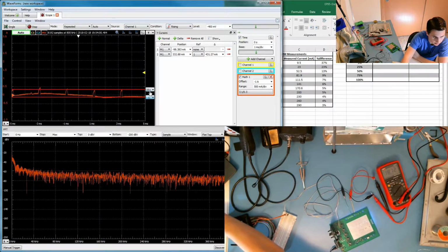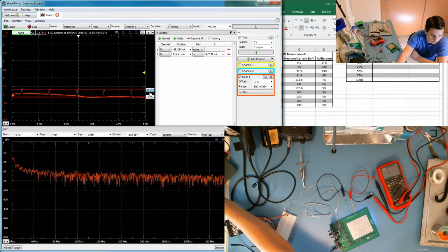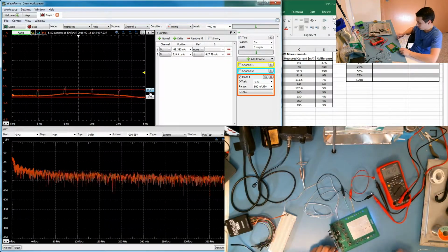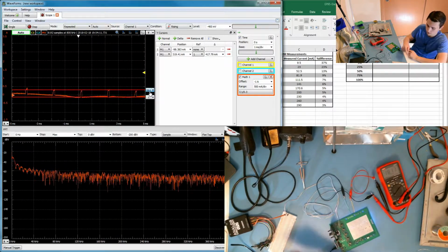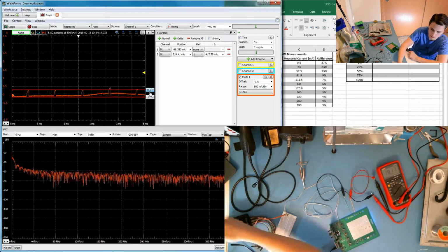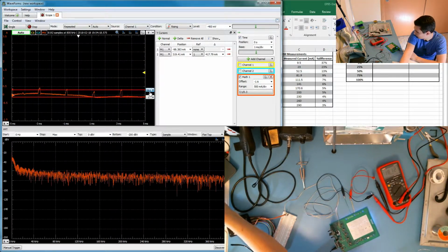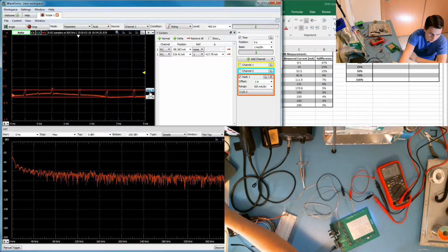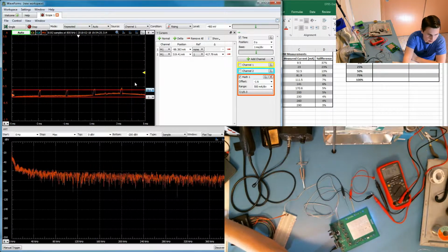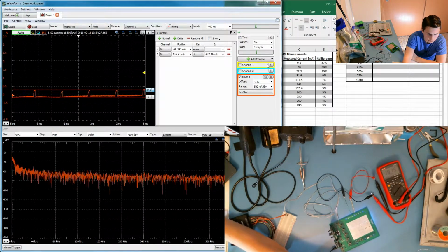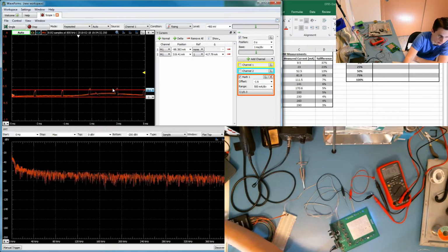In fact, you'll have to excuse the noise. This isn't a fully differential setup, and I think there's some AC coupling through the power supply onto the DC rail, and this is referencing ground of the computer, so there's some noise there. I could try AC coupling. That's all right, I'll leave it. It's fine the way it is.